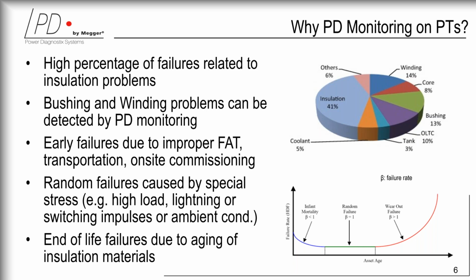And how do we do that? Generally speaking, we can look at a partial discharge monitor. This is happening right after the transformer has been built, may not even be filled with oil yet, and partial discharge is being tested at different levels, even on components. And of course, after that, you go through very complex tests.